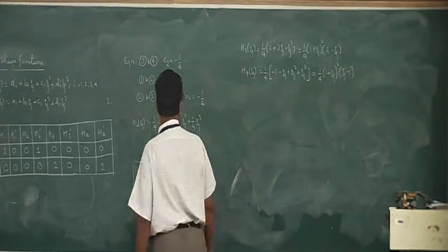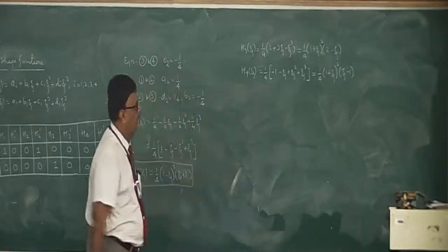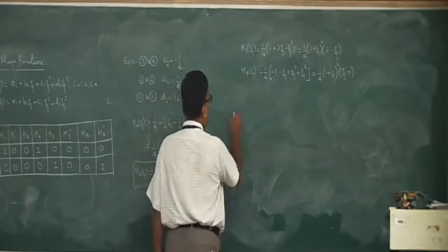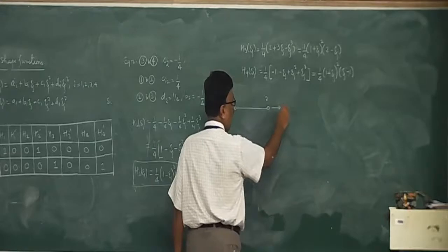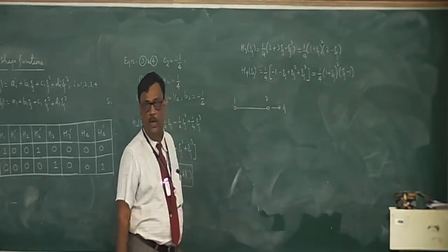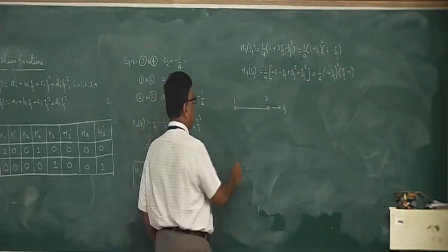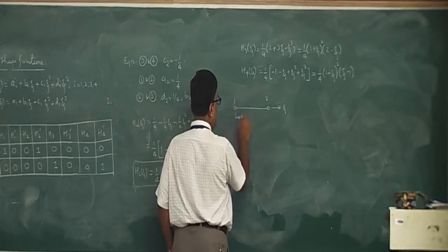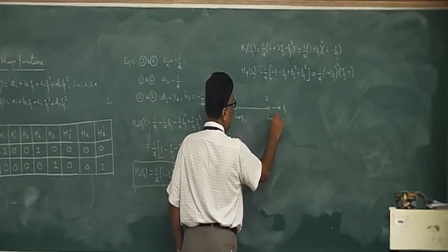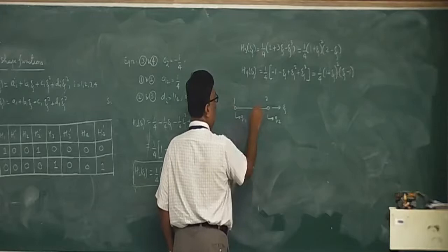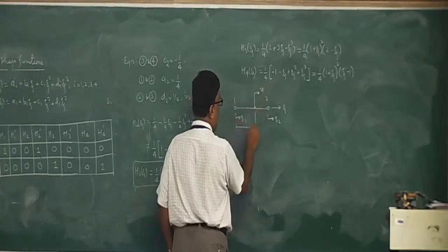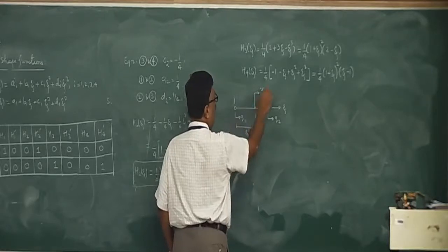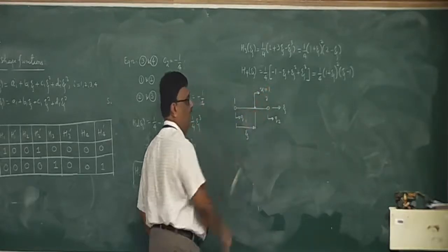See what is the use of these 4 shape functions? Like for example, if you take this as your 1 and 2, in the case of a one dimensional 2 noded bar element, what we have seen? We had seen that the displacement of this node was Q1 and the displacement of this node was Q2. Suppose if I simply specify the value of zeta, how do I find out the displacement of that particular unknown point?